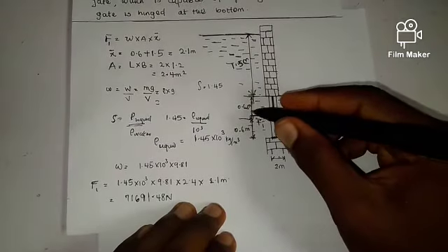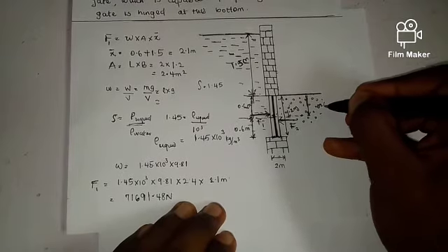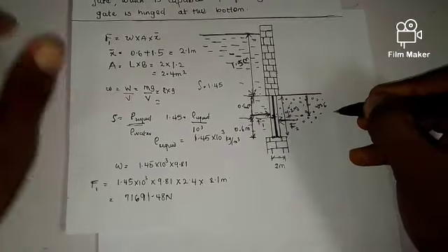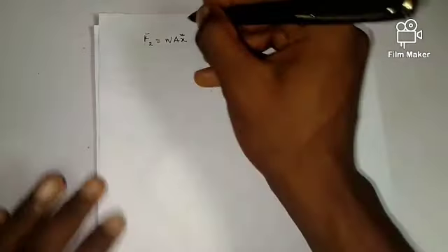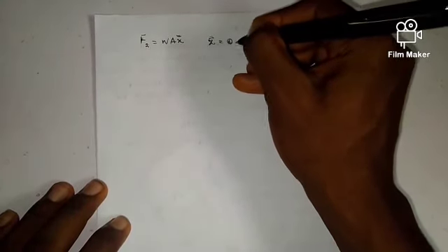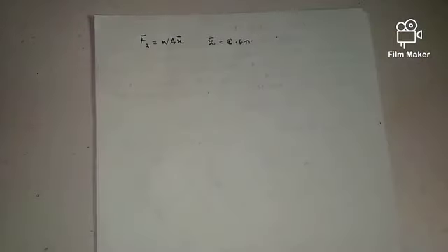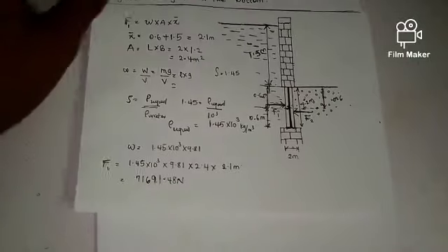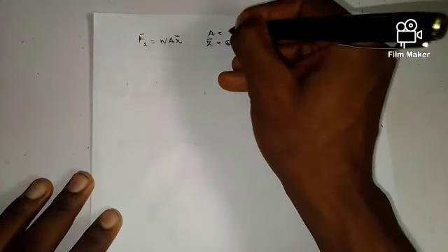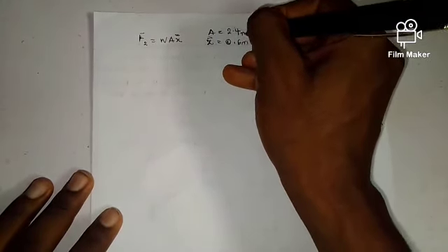So from here to here, we know that is 0.6, right? So basically my depth from this liquid surface to the center of the body is 0.6 meter. So I can basically say my x bar is equal to 0.6 meter. Is that taken? So next up is my area. Since we have successfully calculated the area of this gate to be 2.4 meters square, I can just rewrite it as my area here is equal to 2.4 meters square.